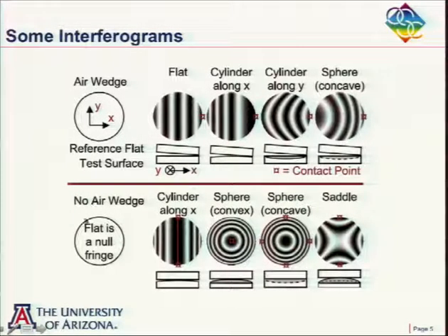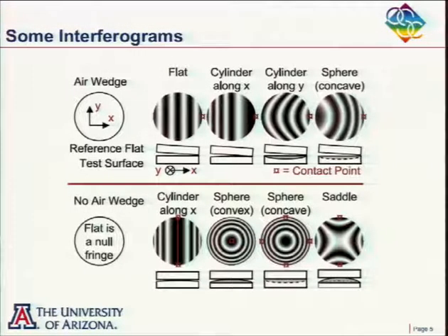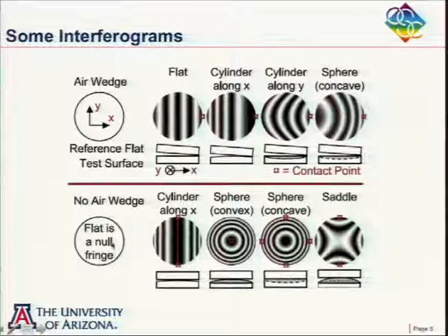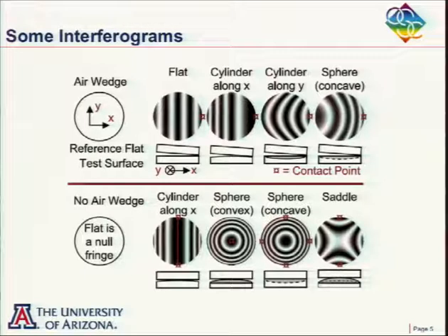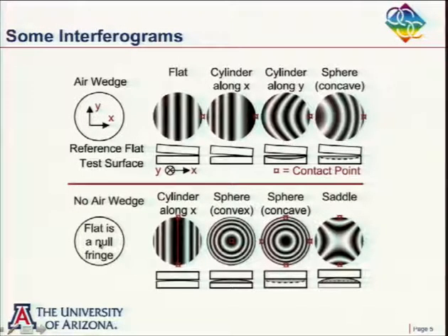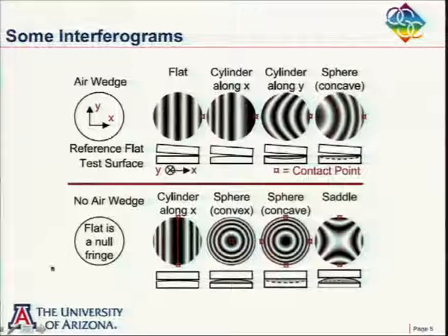And if you're trying to measure errors by looking at how straight the fringes are, of course this isn't going to work, but if you're using phase shifting, you fluff out the fringes. Because remember in phase shifting we always get this double frequency error. If the calibration is off just a little bit, we always get an error that is double the frequency of the fringes. Well, if I have one, then I don't have the problem with that. And so with phase shifting, you generally fluff out the fringes the best you can.